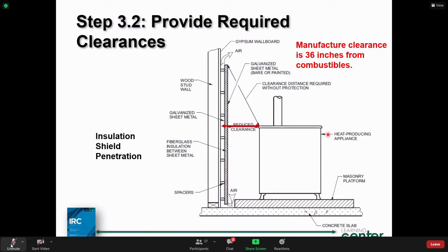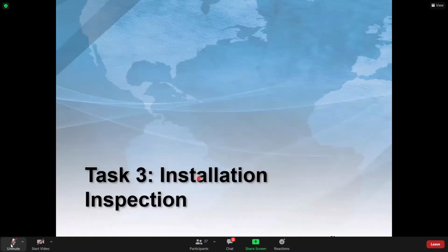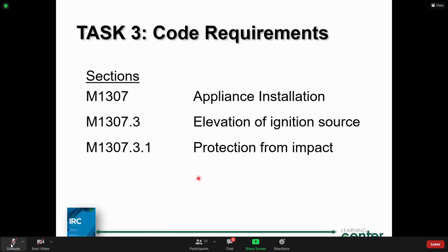Does that help? So in other words, if you're an inspector and you go out and you see some of this stuff, you know what? You have a solution. Just don't go out there and say, oh, it fails miserably. You got to move that thing out of there. You know, put on your education hat. Say, you know what? Maybe the manufacturer would allow a clearance reduction method. You know, they have materials now that you can actually adhere to the wall surface. They're listed clearance reduction panels. They're cementitious and you could actually fasten them to the walls. All right, so understand that that exists, ladies and gentlemen. And there's also a table just like it in chapter 24.